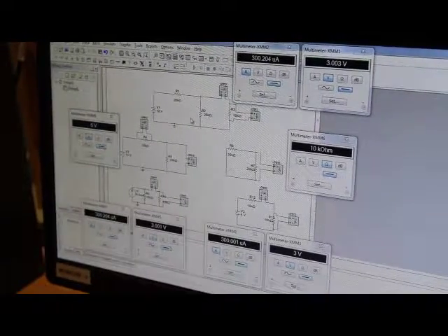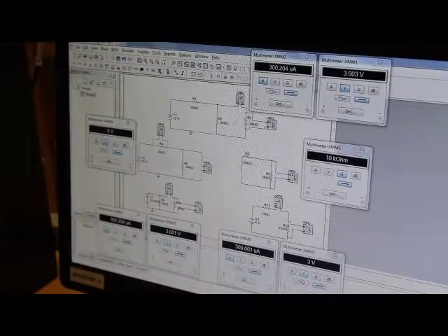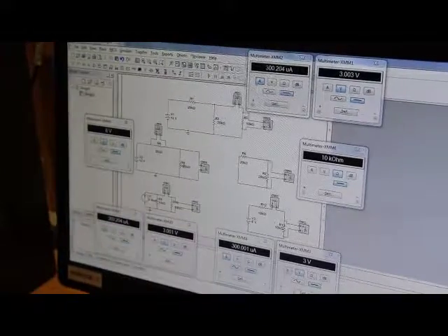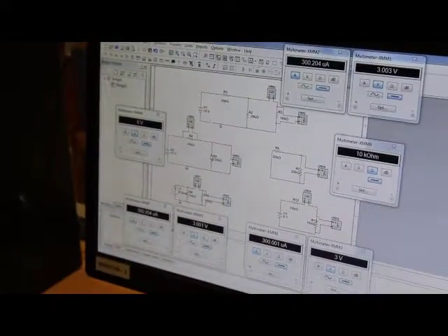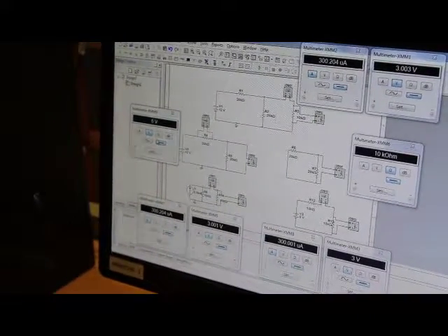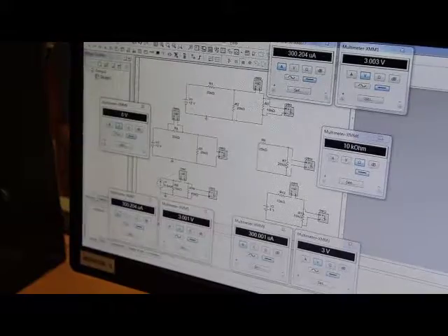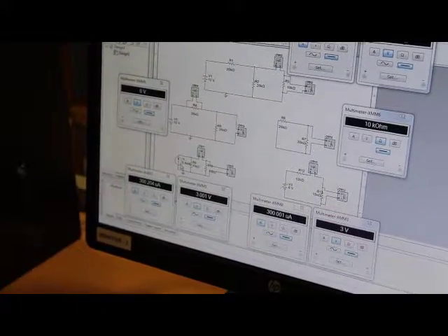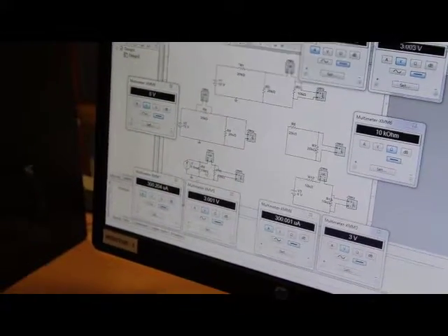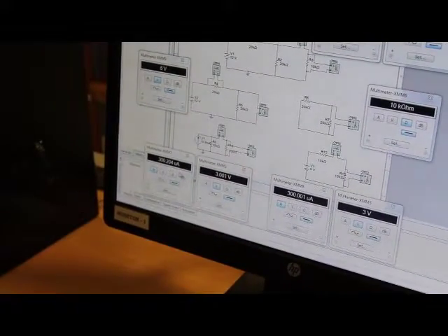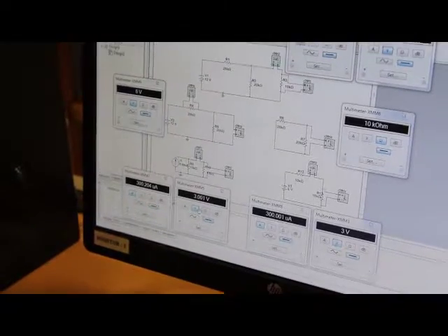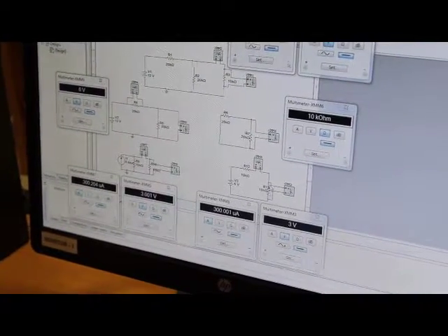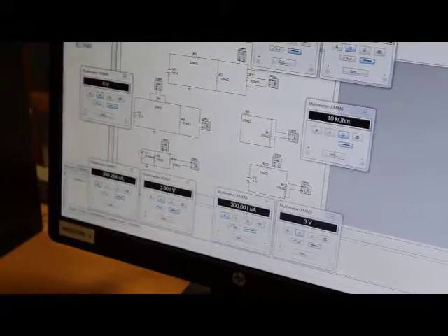So this is the sample of the circuit. This is the initial circuit. The current is 3 microampere and the voltage is 3. And this is where you want to measure the Thevenin voltage. The Thevenin voltage is 6. And this is the Norton resistance. Norton resistance is 10 kilo ohm. And this is where we want to measure the Norton current. Current is 3 microampere and the voltage is 3. This is the comparison with the Thevenin circuit. The result is the same as the initial.